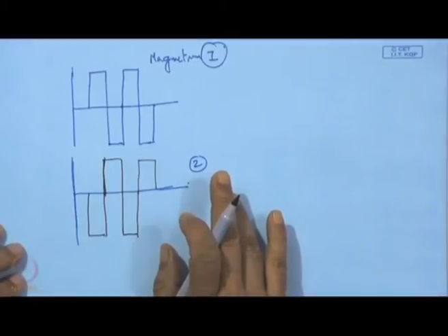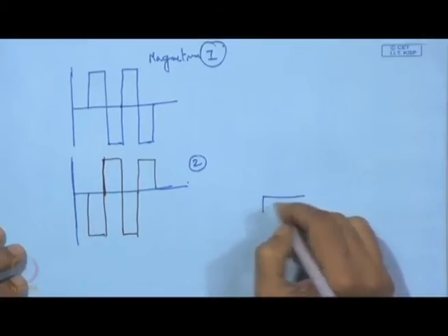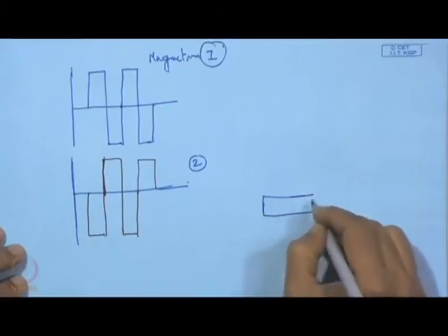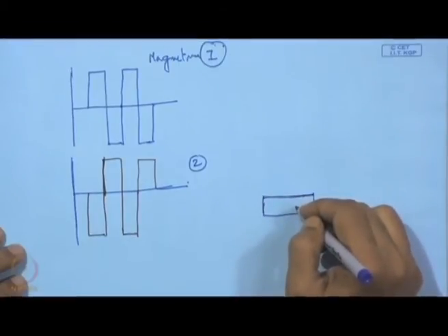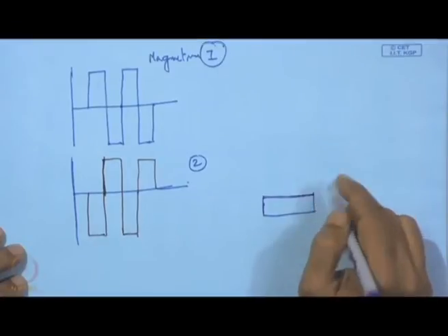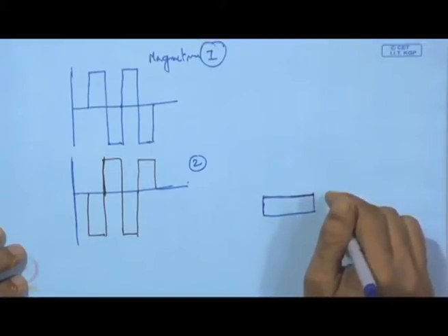In fact, in all these machines we can have the pulse generator for 2 targets or we can have 4 targets. Even the substrate can have this pulse generator supply, because the substrate surface may be a conductor, but once a non-conducting film is deposited on the surface, then the DC supply will not work.